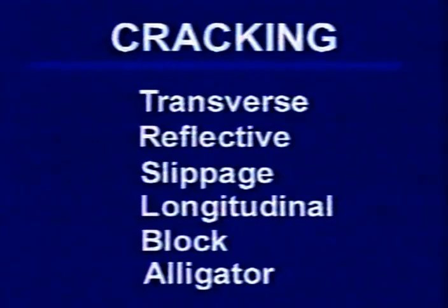Sometimes we have large objects, boulders, stones, or whatever, buried in our pavements, and with the advent of time and frost action, these objects tend to work their way to the surface. Here you've got an indication of a boulder or something that's actually pushing its way up through the surface. And you'll have to simply dig this out and make a spot repair. But it's another indicator of a frost action problem.